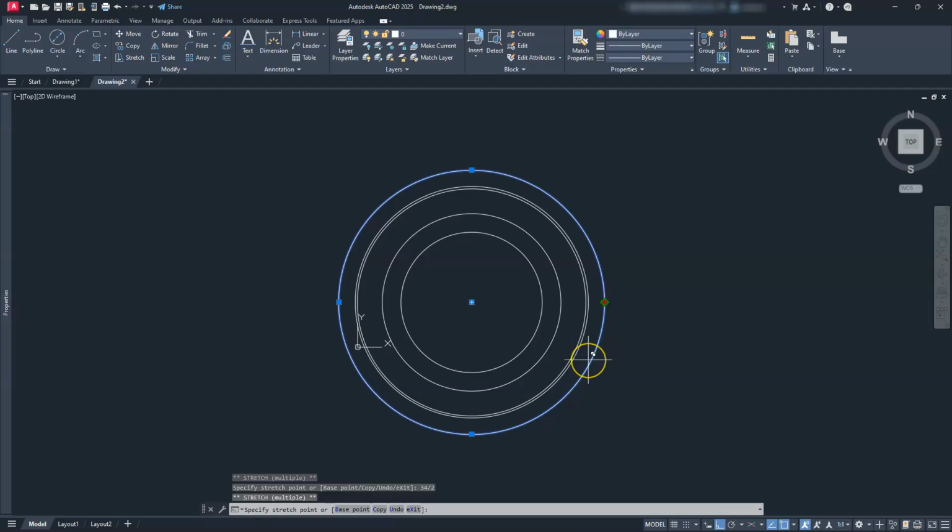The reason I have to divide it by 2, and let's go ahead and escape out of this, is because we have to type in the radius, right? So it's looking for a radius. Radius is half the diameter. In our drawing, everything is given to us in diameter. So therefore, I have to put in and divide it by 2. And that's also the reason why this works really well. But if you have decimals, you got to kind of convert things and move decimals over.